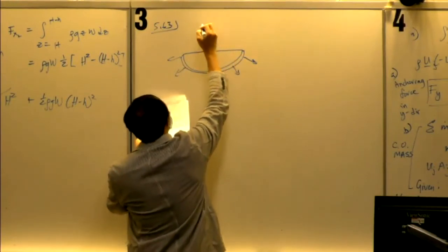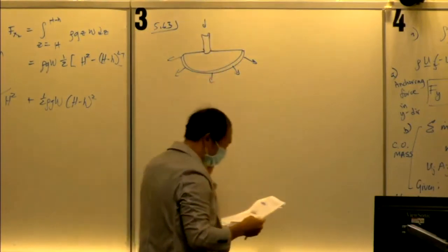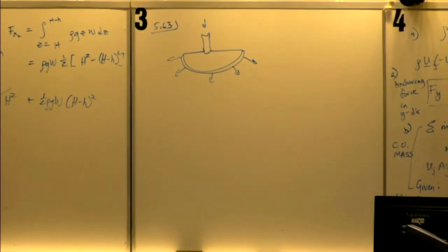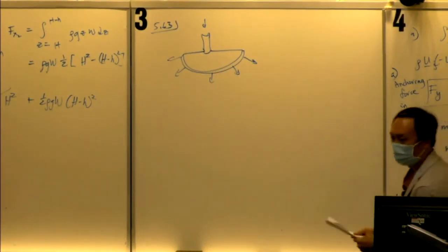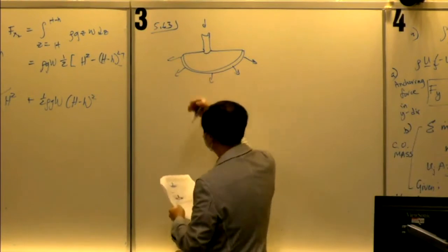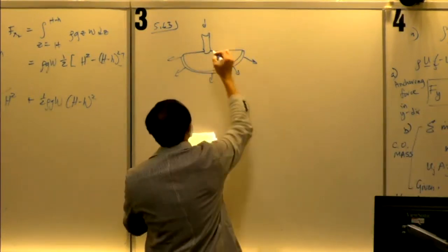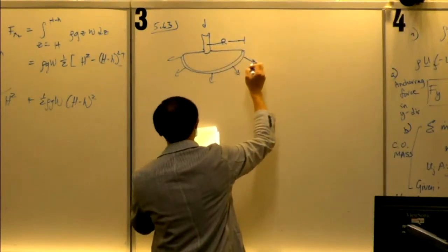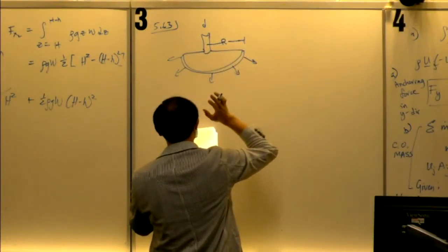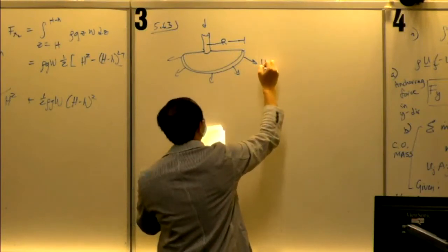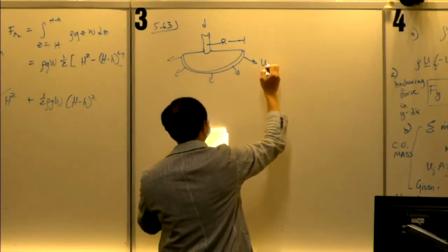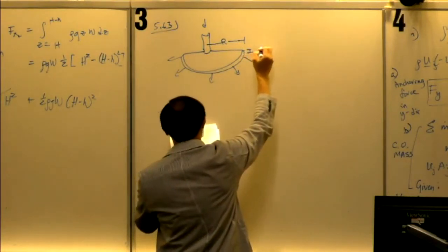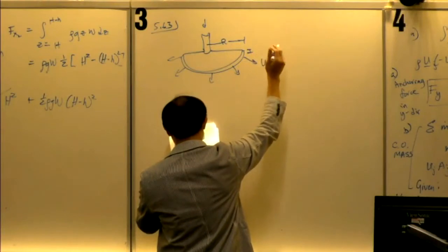All right. So fluid's coming in and it's spraying out, but only in the half plane. So it's in the half plane, that tells you immediately there's going to be a force, because fluid doesn't like to be sprayed out just in the half plane. They give you this R, and they give you the jet velocity at the exit, uj, and they give you this height, h.